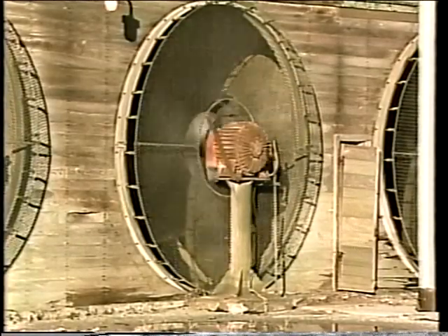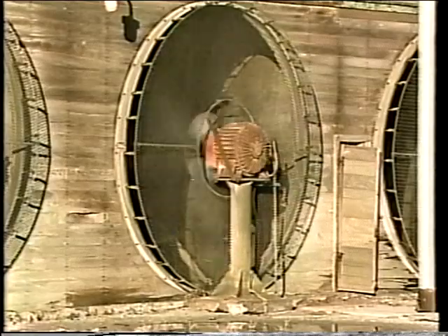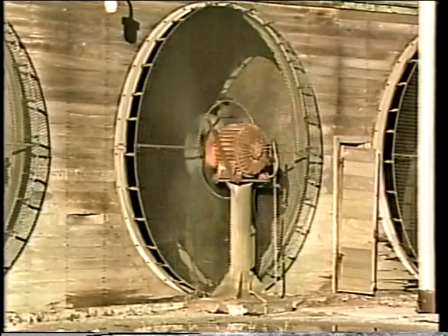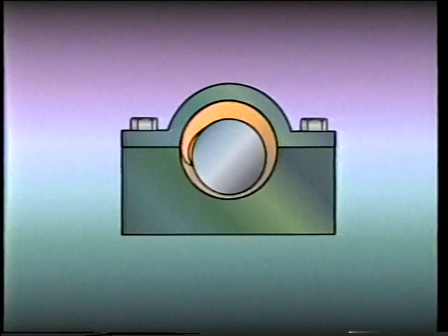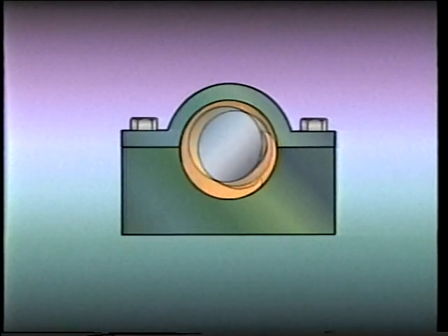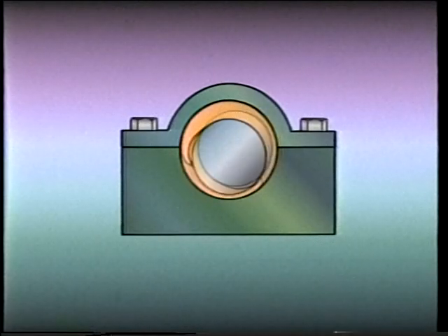Sometimes vibration occurs when the fluid flow near a fan or impeller is disrupted by a stationary object in the flow path. A condition called oil whirl can develop when the liquid surrounding a bearing or a mechanical seal starts to spin with the shaft. The spinning liquid can move the shaft and cause vibration.